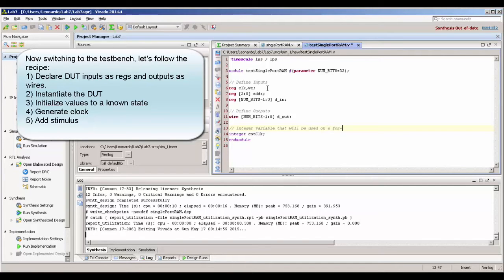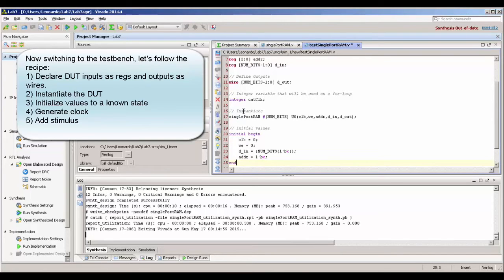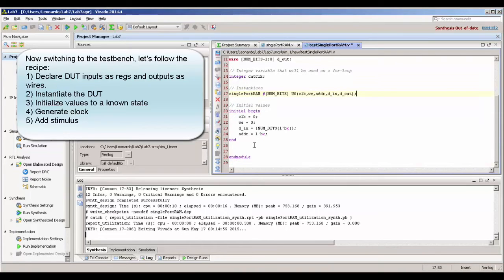We just write a known value in all memory positions, then we read and verify that the values match. Then we try to write in a previous position that we wrote before, to verify if the single port RAM that we created is in write before read or read before write mode.